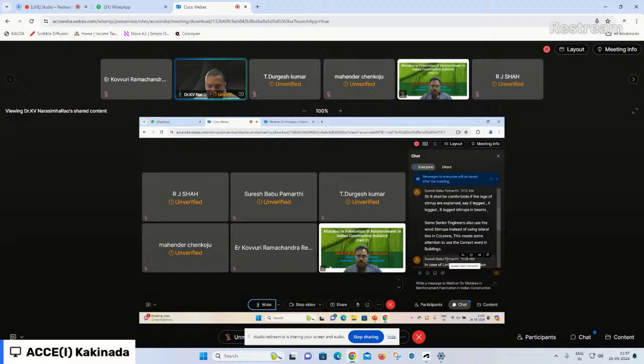If you are not providing in that fashion, you have to construct a lintel beam and place the top steel of the sunshade in the form of a loop, which forms around the lintel beam, around the main steel, that is the four bars of the lintel beam, on the outer side, similar to a stirrup, such that the development length requirements are met.